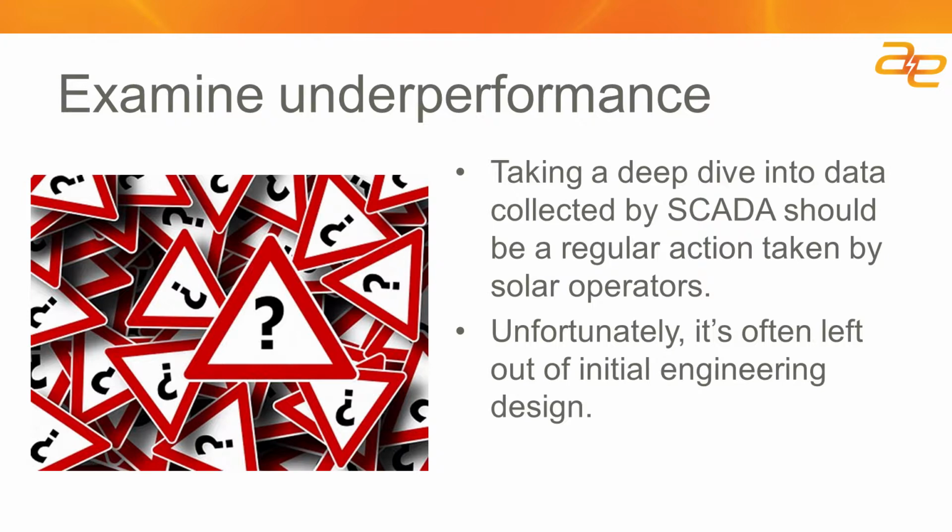One of the things I encourage my engineers to do from time to time is to just pick a topic and do a deep dive on the data that's being collected to see if it makes sense, to see if the inverter current is changing over time, to see if the kilowatt hours from the inverter is changing on a day-to-day, week-to-week, month-to-month basis, and see if that aligns with what the overall site performance is.